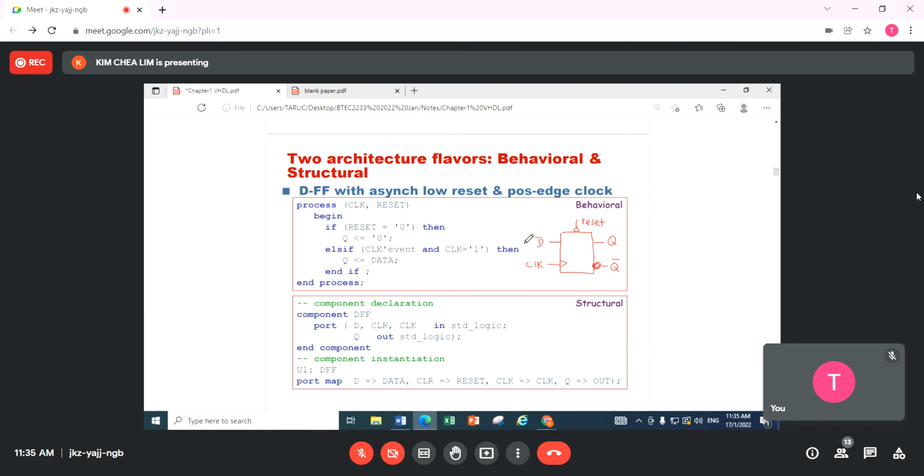When we are dealing with a flip-flop as a real component, every time my clock comes, my flip-flop will work one time. Depending on the type of clock that they respond to, in this case it is positive edge. That is to say, when the rising edge comes, the D flip-flop works one time. Another clock rising edge comes in, the flip-flop works another time.